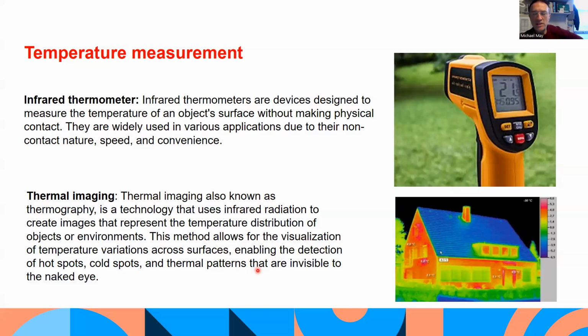So if you wanted to get a building energy rating value on your house, people might use a thermal imaging system and look at your house like this. For example, you can see that the roof must be well insulated because it's not leaking any energy, but the gable end here is releasing a lot of energy coming out of the house. So you might need to insulate your house to improve your building energy rating value. And then you can repeat the thermal imaging process afterwards and see if it improves.